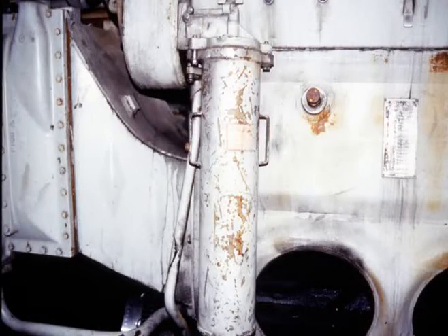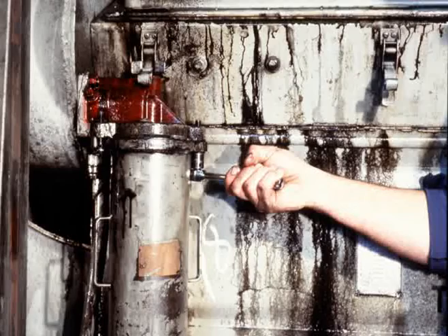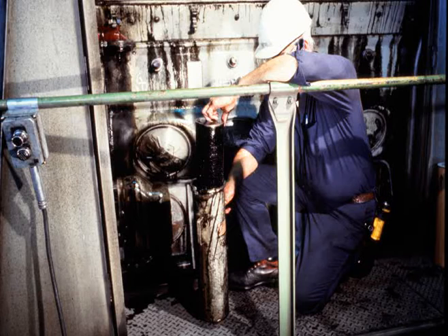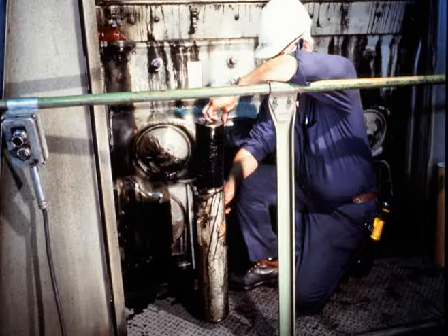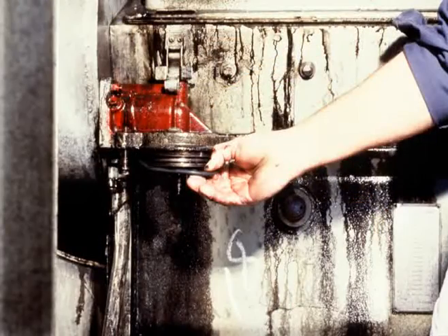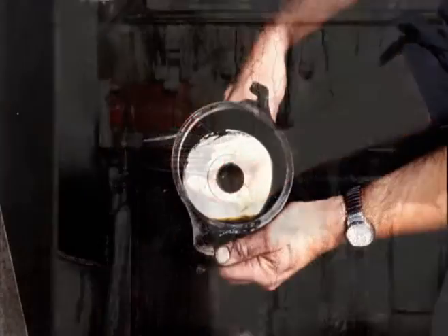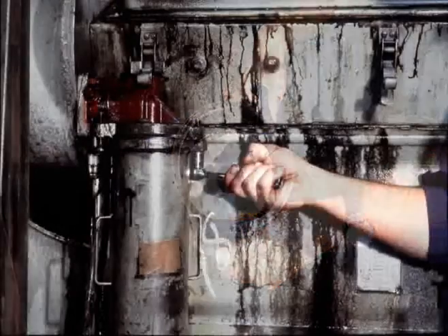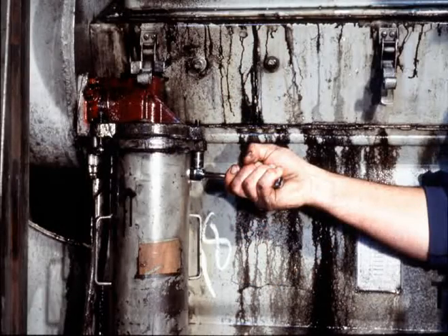The last item in our maintenance is the turbo filter. Loosen the two bolts holding the canister to the filter head. Carefully remove the canister and examine the filter for any signs of metal particles. Replace the seal and install a new filter. Replace the assembly and tighten the two bolts. Do not over-tighten.